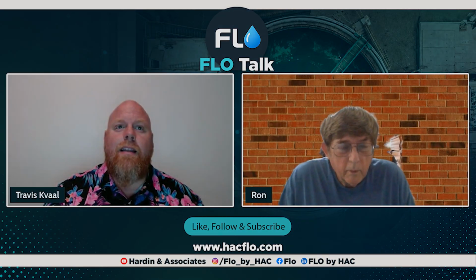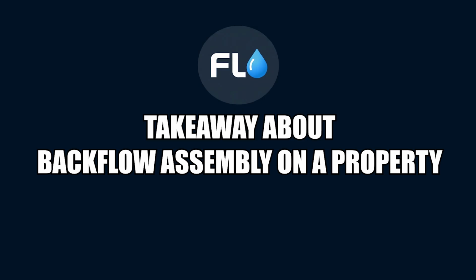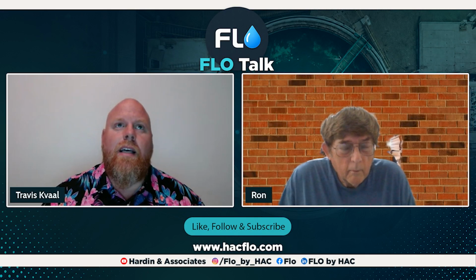Oh, yeah. I think one of my biggest takeaways is that a backflow assembly on a property doesn't necessarily mean that property is protected. Right. And like you talked about, even if I have the proper containment assembly, I've got to protect the folks internally inside that facility. So making sure I have the right level of protection at each point of use, where we use water for different cross connections and hazards, is important. And the other thing is that these properties change over time and use changes over time, and we need to monitor that continuously.